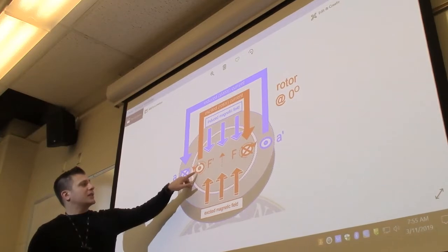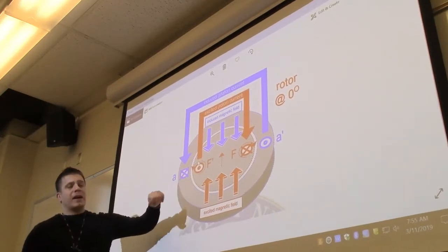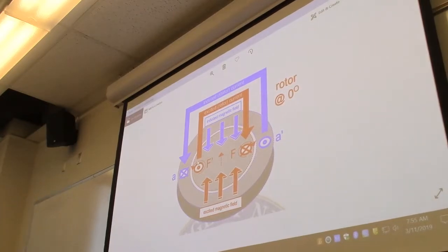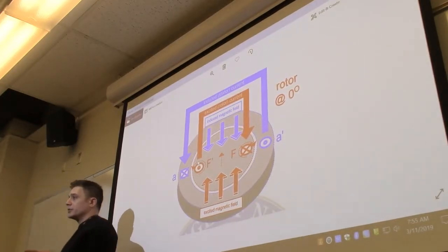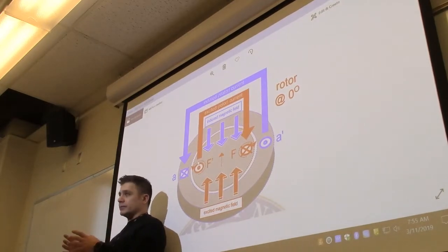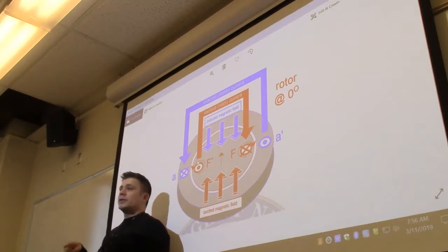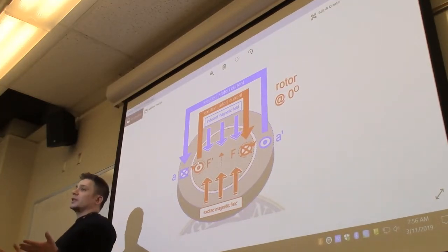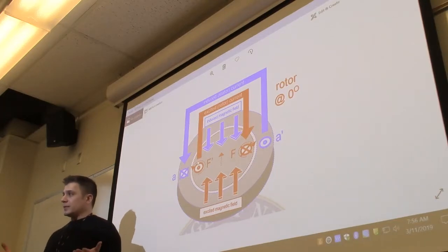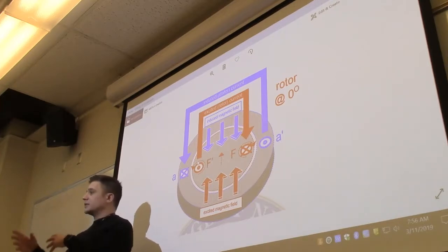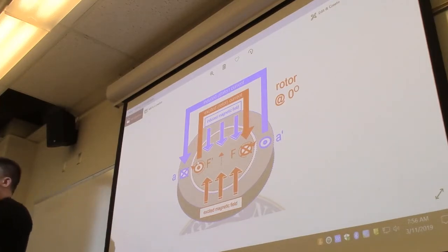the flux linkage between the field winding and the stator winding is going to change, right? Our goal is to excite a voltage or generate a voltage differential at the output of the stator terminals. So if the generator didn't turn, the flux linkage would be constant, which means there wouldn't be any voltage generated. So it's the rotational motion that actually causes the dλ/dt.